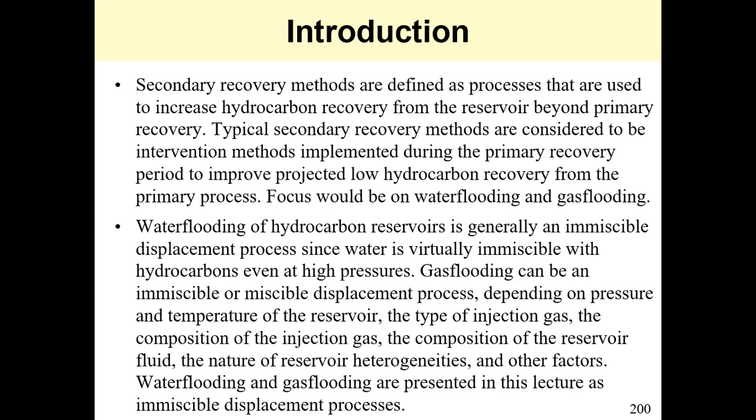So our focus would be on immiscible water flooding and immiscible gas flooding. Water flooding of hydrocarbon reservoirs is generally an immiscible displacement process, since water is virtually immiscible with hydrocarbons even at high pressures.